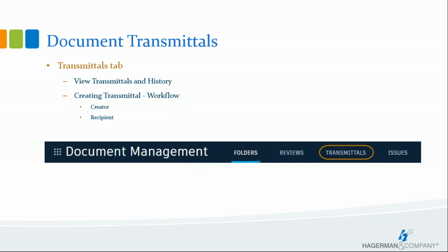The transmittal feature in BIM 360 is for generating and tracking document transmittals. Transmittals are now available to both the design and the construction workflow, as I mentioned before. We'll take a look at viewing the history of transmittals as well as creating a new transmittal. The transmittal creator defines which recipients will automatically be notified by email of the new transmittal. Recipients can select the link in the email to go directly to that transmittal, or access the transmittal from the transmittal tab in Document Management module.